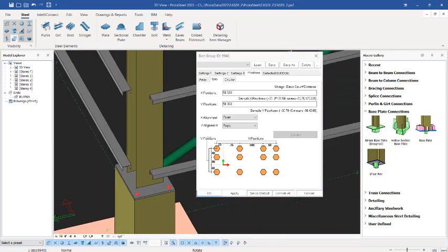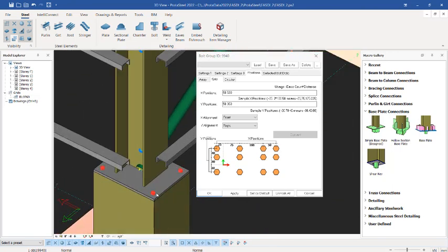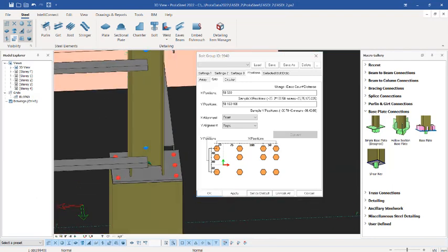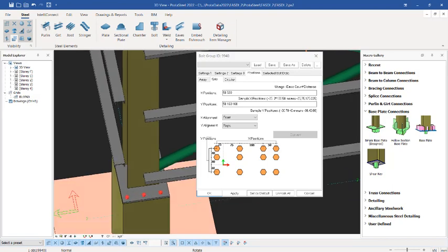So we have placed a bolt just like this. If you want to have more bolts in this Y direction, you can actually divide this by 2. Let's say you can still have 150 or 160 right there. You give a space, you have another 160 right there. If you click on apply now, you see you're having 3 bolts right there. If you check this side, it's the same thing, 3. So I believe this is fully understood.